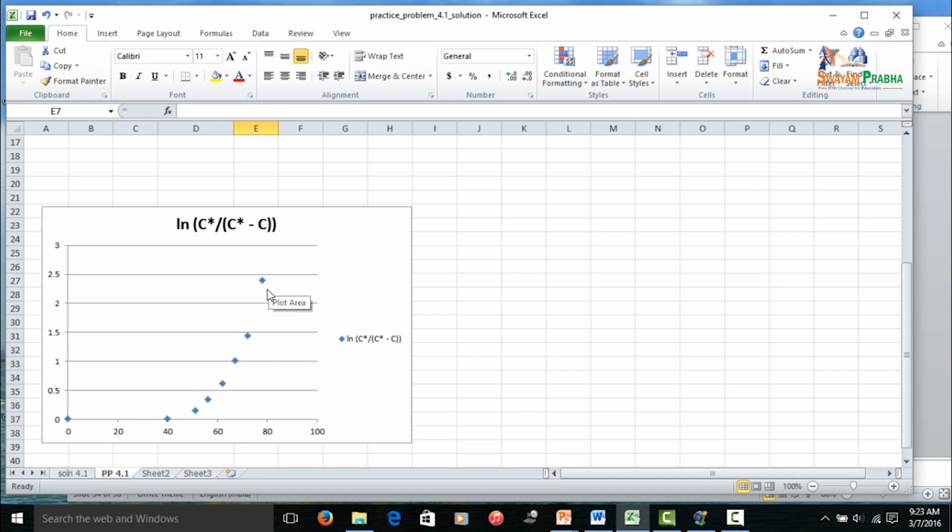However, we can use that particular equation only in the linear regime for oxygen sorption. This is a non-linear regime here, that is to be expected. The linearity probably starts here and goes up. Therefore, we are going to look only at this region for calculation of KLa, only at the slope of this particular region.